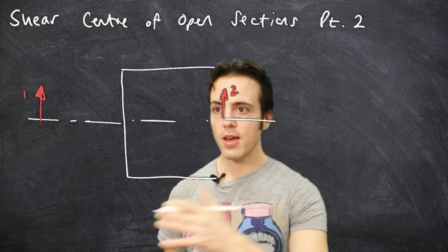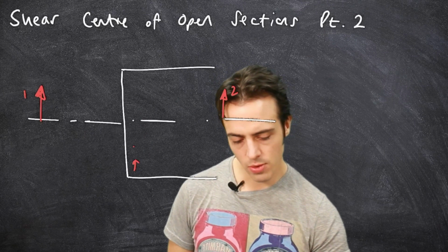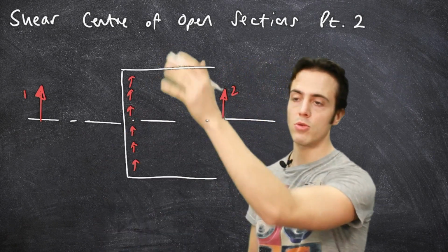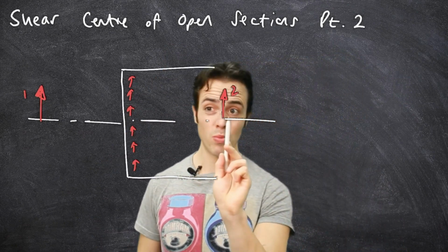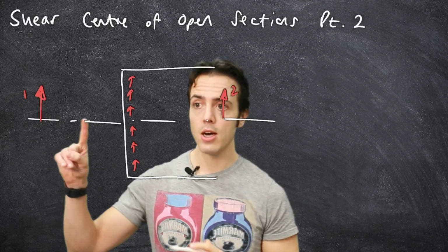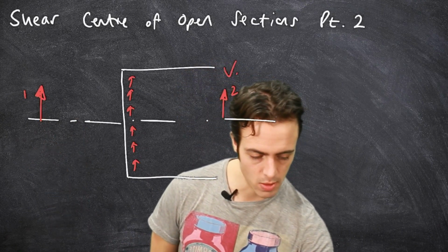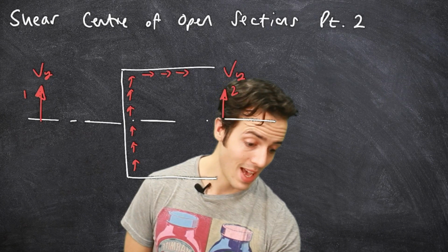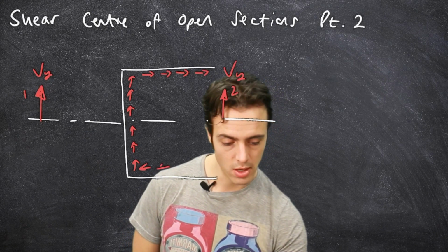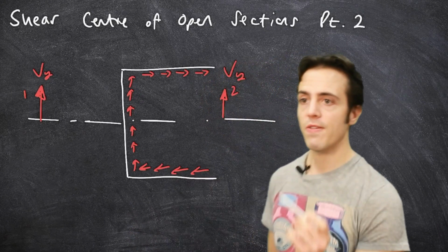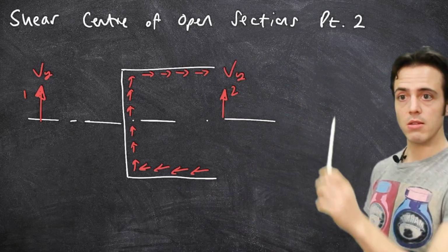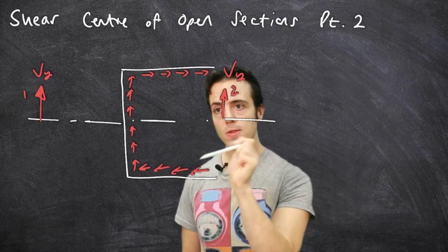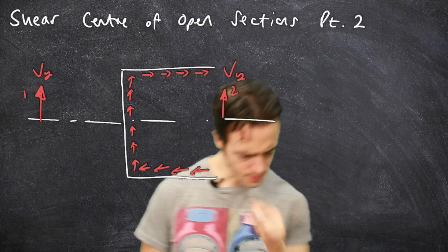We know that those internal shear flows, the internal action flows, are going to exist like this. So we've got the vertical one that's aligned with the main member because it's aligned with the shear force, whether I apply it here or here. Let's just write this as Vy. We know that from the continuous distribution that we have to have, the shear flows have then got to have this direction. So it follows that if I load this C section vertically and in a positive direction, I will always have a sort of clockwise motion to the internal action shear flows.